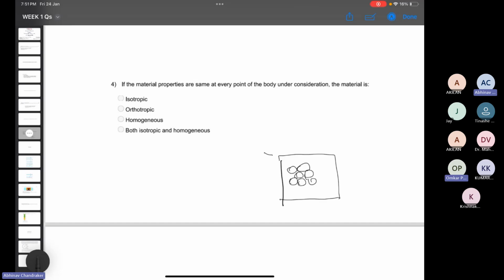For example, let's say you have a metal. Since my work is more involved in metals, I can give you an example related to that. You look at it at high resolution, you see that you have particles embedded in it, which is very common. Let's say these are some oxide particles or some reinforcement particles. So this is a particle reinforced composite having a metal matrix. Then this is not a homogeneous material, right? You have two different components. You have this hard, let's say a ceramic particle, and this much tougher metal matrix, and this is heterogeneous.